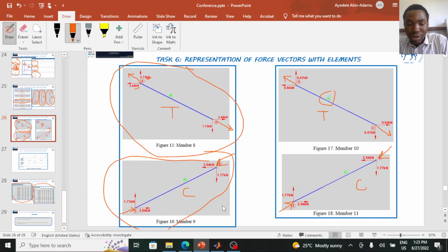This is how you analyze a plane truss problem using the finite element procedure in MATLAB. And as I said in the beginning of my video, in the first part, the finite element procedure is very similar to the stiffness matrix method of analysis. The stiffness matrix method of analysis is another method of structural analysis in the field of civil engineering. So the finite element procedure is actually very similar to the stiffness matrix method.